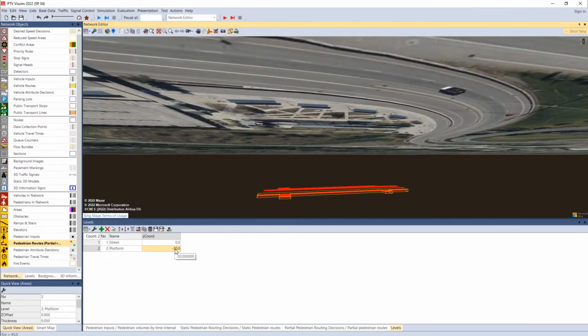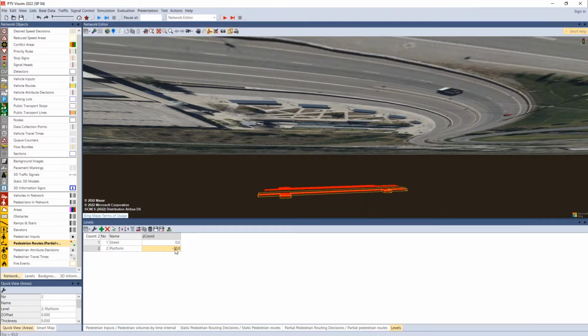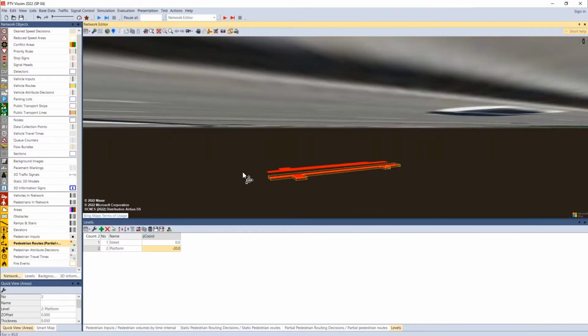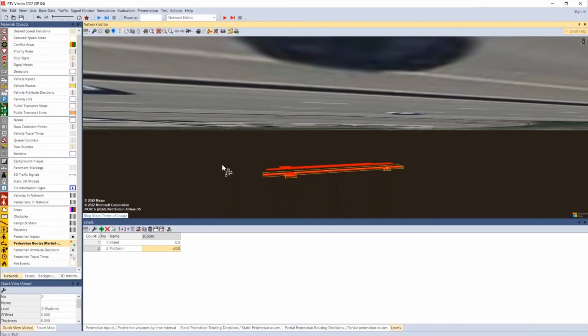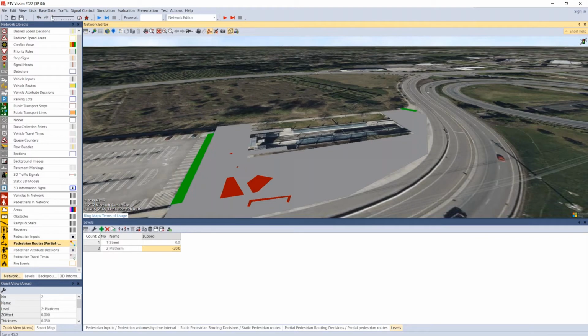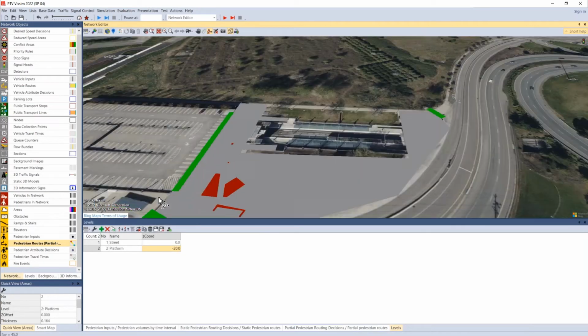And you can actually see that I can move my level offset dynamically in real time, so that way we can establish where we want everything to be, right? So we're at negative... I guess I'm in meters, so I need to switch my units over to feet because I've been typing in 20 meters. So I'm going to switch my units real quick over to imperial. And so this should actually be negative 20 feet. There we go. That's much more realistic.